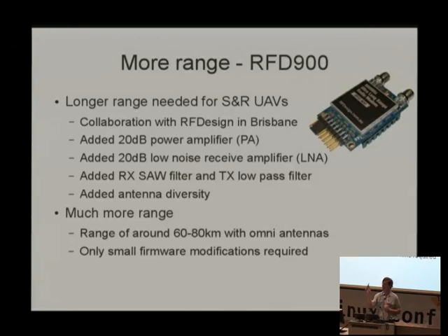So two antennas with antenna diversity, and it pushes up the power, so it can do 30 dBm legally in Australia, 36 in the US because of the quirky rules. You get ranges easily of sort of 60 to 80 kilometres with Omnis. In fact, probably a lot more. If you wanted to go out and do a test, you'd almost certainly get 120 to 150 kilometres if you can get line of sight. It's a little bit tricky with the curvature of the earth and stuff. You need high hills.